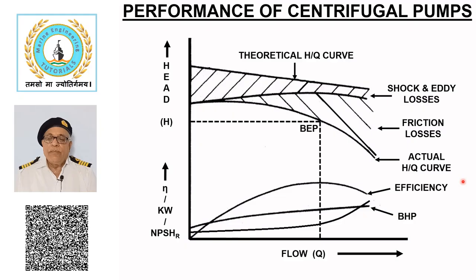Centrifugal pump is thus always started with closed discharge valve, which helps in reducing the starting torque or current of the prime mover or electric motor. As the pump's maximum pressure with discharge valve closed is moderately above the pressure at best efficiency point, a centrifugal pump does not require a relief valve.